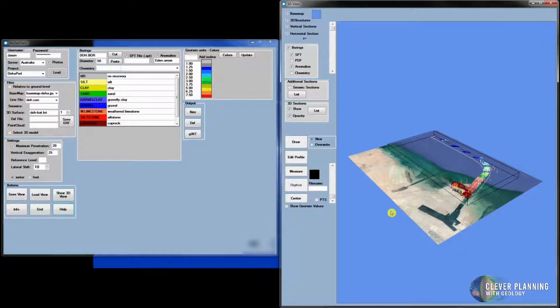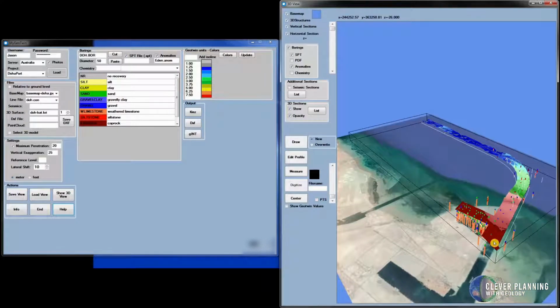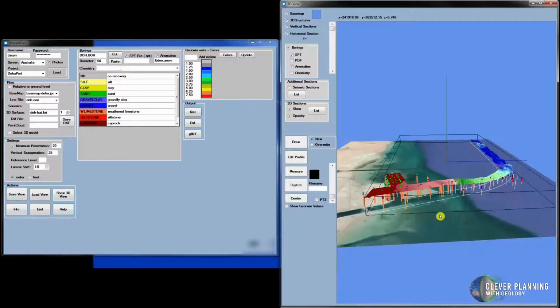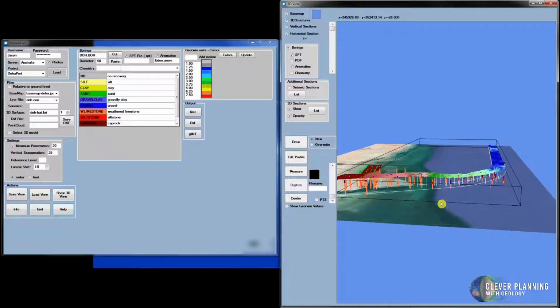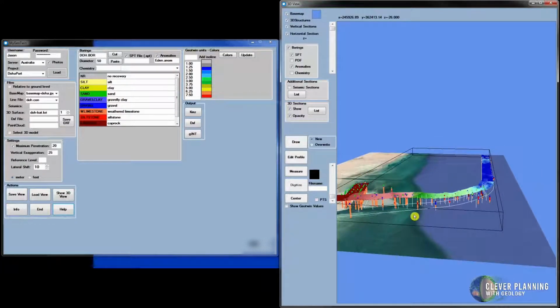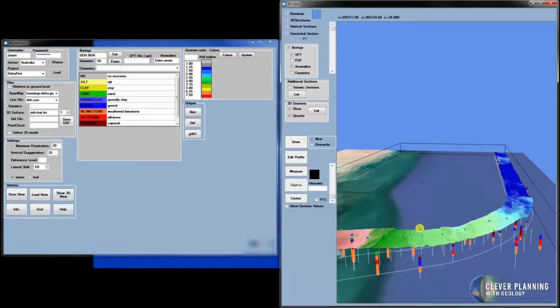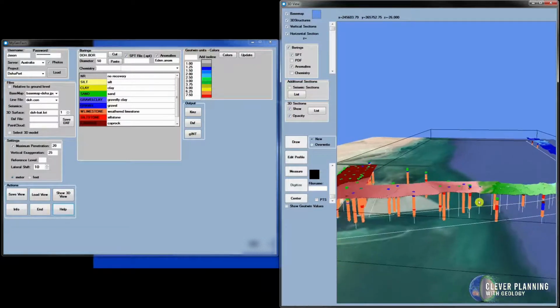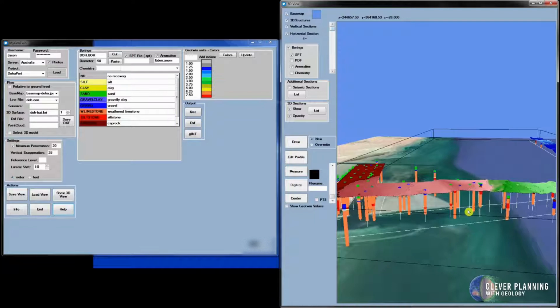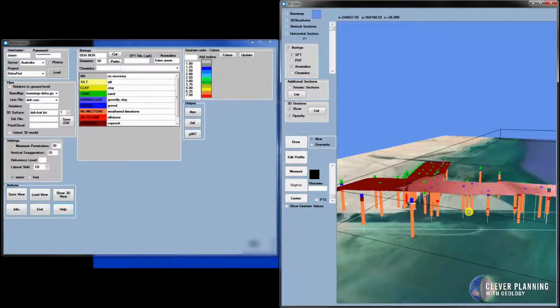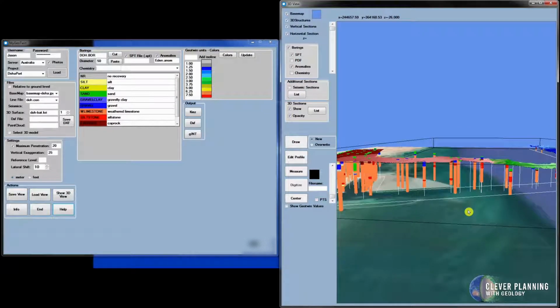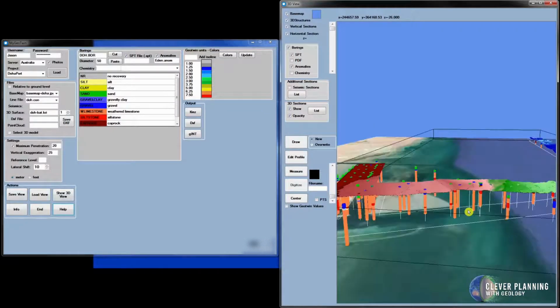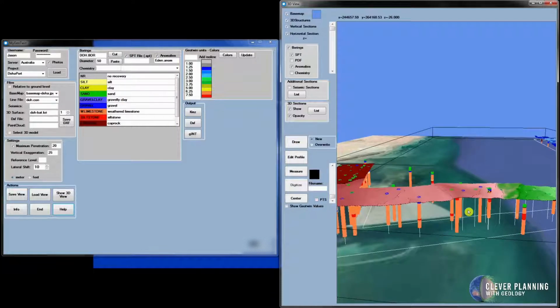Once comfortable, start to move around in the model space. It is best to use a mouse. The wheel will zoom in, the left button to rotate, and the right button to pan. Some functionality is available on the keyboard with the left key and the right key and the up and down buttons. Also, you can use the I and the O buttons to zoom in and out.